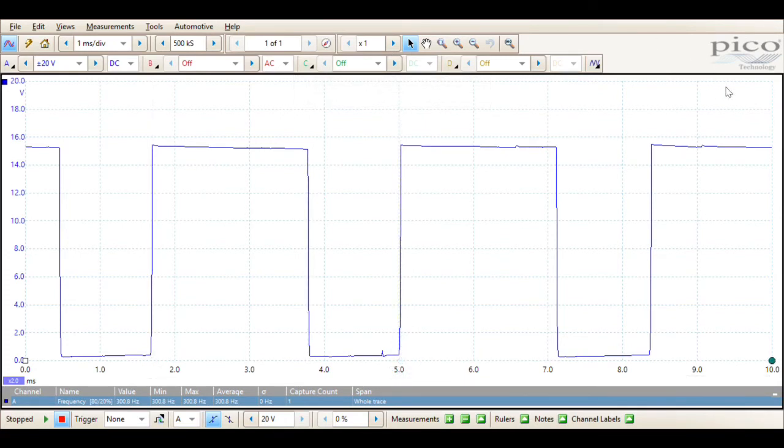Now we're going to discuss our last term, which is frequency. Frequency is the amount of times something happens per second. Okay, a great example of frequency would be like a GM mass airflow sensor, or even a crankshaft position sensor. Frequency can be converted into RPM. So the engine looks at the crankshaft position sensor, counts how many times it sees those teeth pass by, and uses it to calculate the RPM.